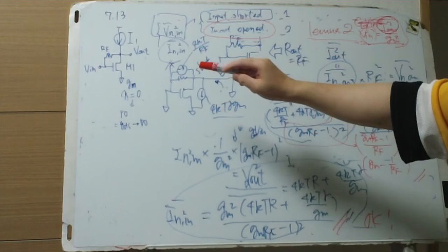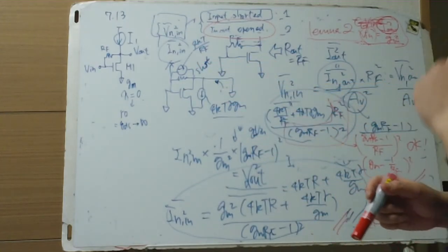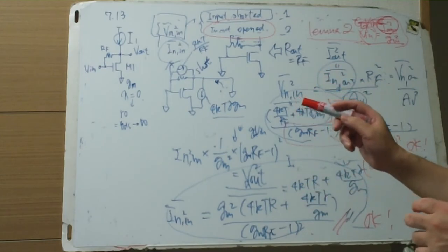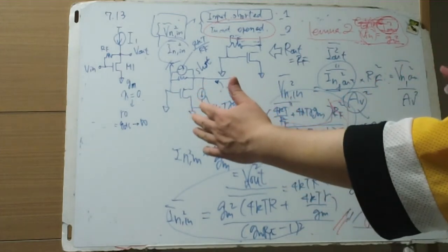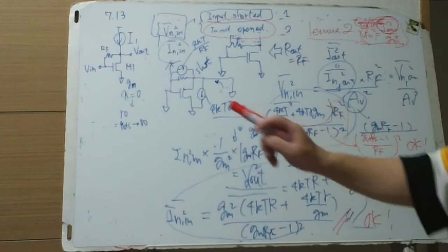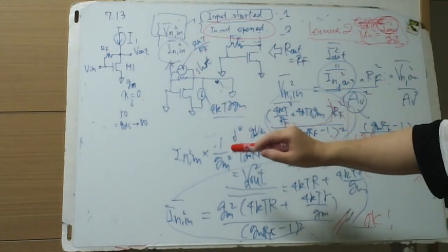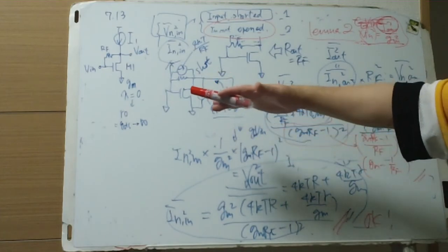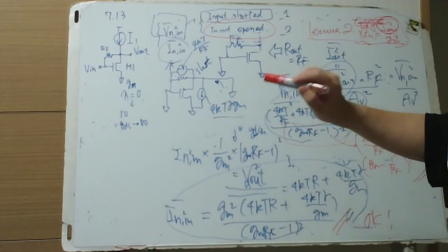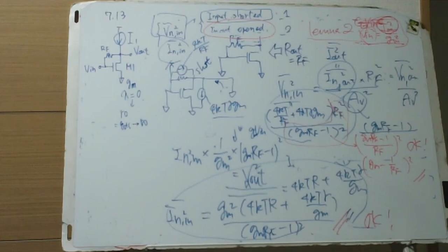Generally these are voltage gains, the DC voltage gain, considering only low-frequency noise. Then sum up the noise components if non-correlated, and use the spectrum times the transfer function to get the output spectrum.